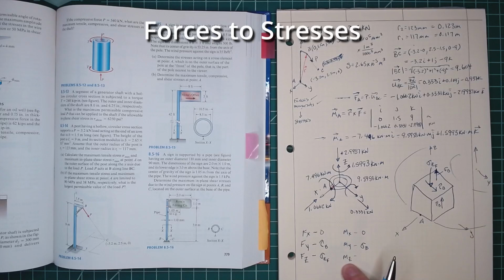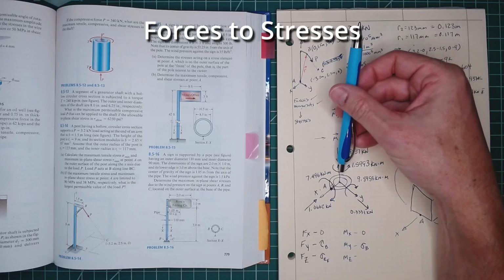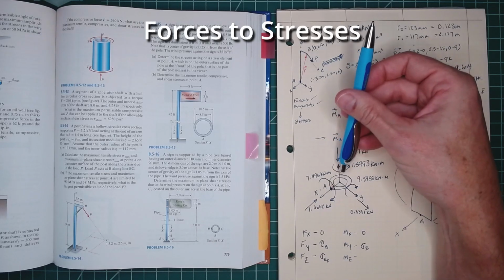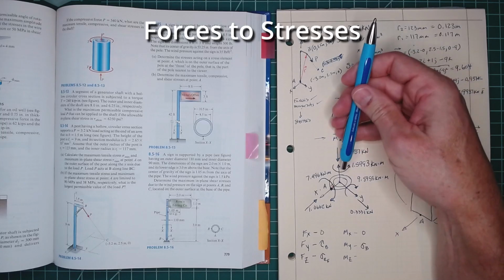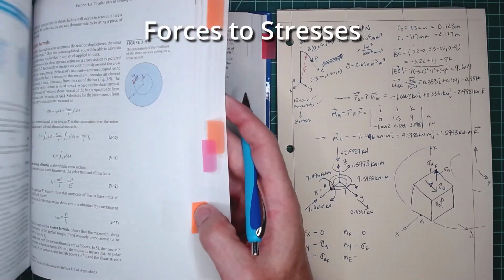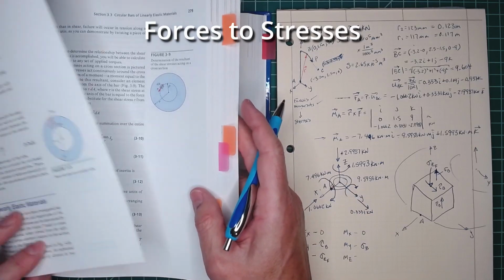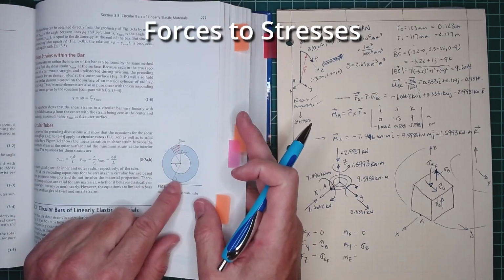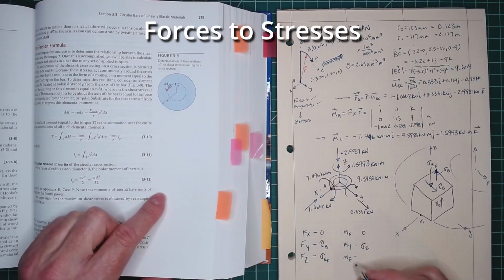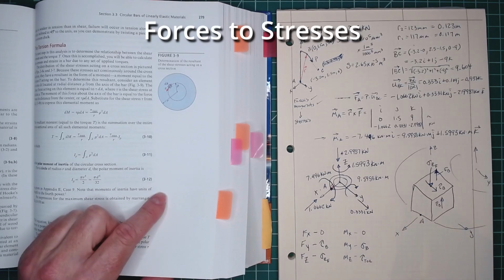And then finally, we have our moment about our z-axis. What's that trying to do? It's really trying to twist. It's trying to torque this, to rotate it in plane. And what is that? Well, when we rotate in plane, that takes us all the way back to chapter 3 on torsion. So we're going to be dealing with torsional stresses. So moment Z is going to create a torsional stress.